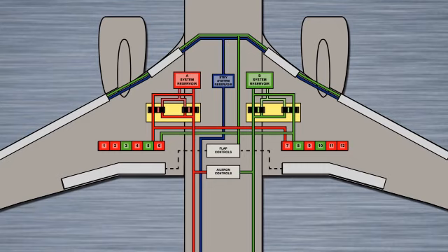It's important to know the following. During alternate extension, trailing edge flaps may be extended and retracted. However, leading edge flaps and slats may only be extended. The only way to retract leading edge flaps and slats when alternate extension is in operation is by returning to normal operation, provided hydraulic system B pressure is available.